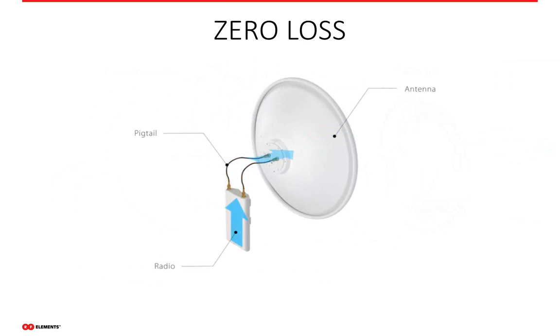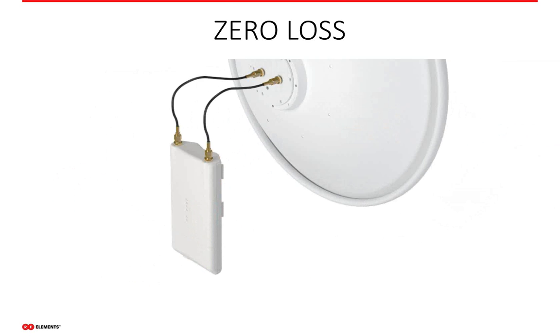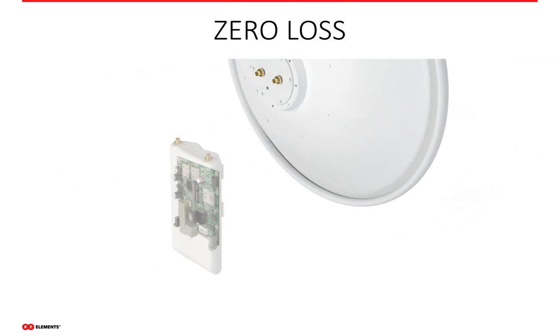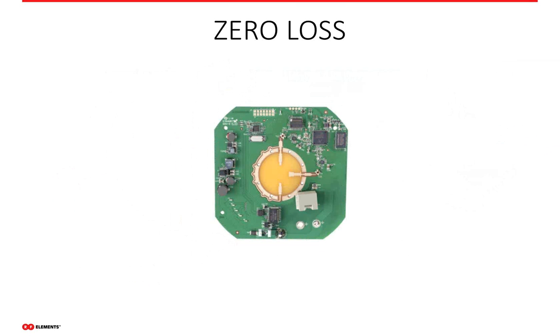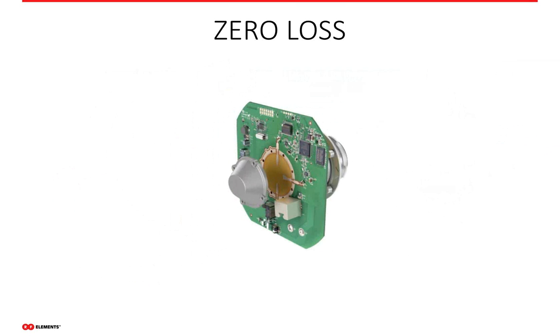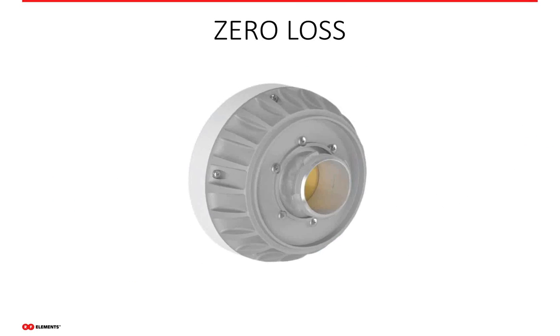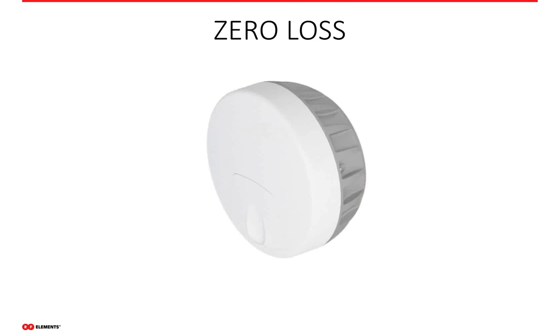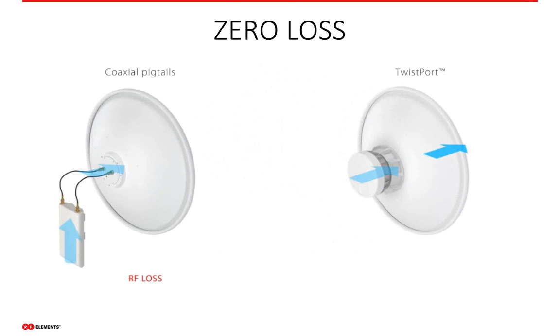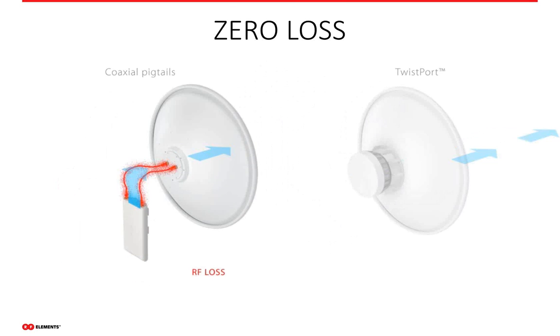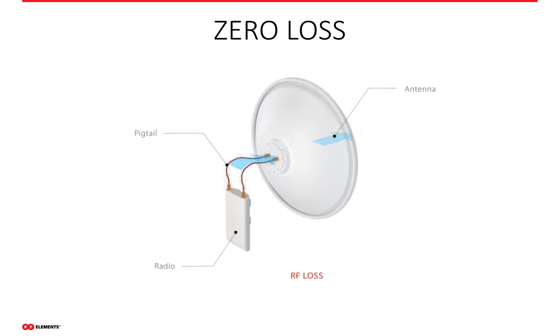And people don't always understand. They think, well, maybe I have 1 or maybe 3 dB of loss because of those pigtails, so I'll simply add another 2 to 3 dB of TX power on my radio, because the radios are capable of doing that and you still stay within your EIRP limits. What most people don't understand is that they're trying to achieve MCS 9, the highest modulation rate in AC, to get the highest bandwidth. But most radios are incapable of sustaining, maintaining, and receiving MCS level 9 if you go beyond like 20 or 21 dB of TX power on the radio.